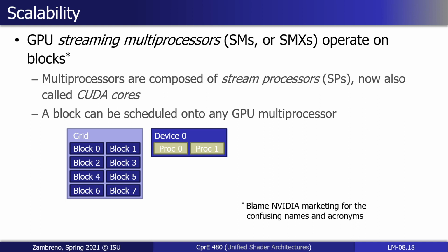And these blocks will get scheduled on individual SMs on a block by block basis. We don't have enough knowledge to know exactly how many blocks are getting scheduled at one particular time. We just know it's getting scheduled on a block by block basis. There are other things we can learn about our individual kernel that'll give us a better hint in terms of how that scheduling is going. In general, we don't get that level of detailed feedback. You have to use a simulator if you want to know exactly how those things would be scheduled.